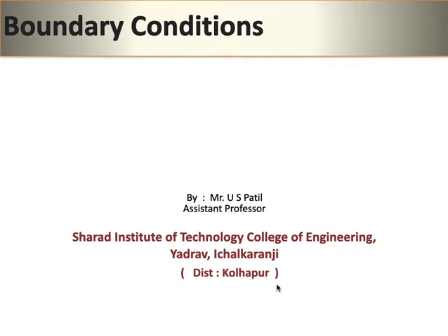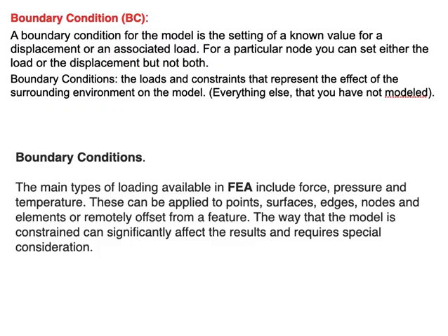Today, we're going to see the boundary conditions in FEA, finite element analysis or finite element method. So, let's get started with the boundary condition. Boundary condition for the model is the setting of a known value for a displacement or an associated load. For a particular node, you can set either the load or the displacement, but not both. It's a very important point.